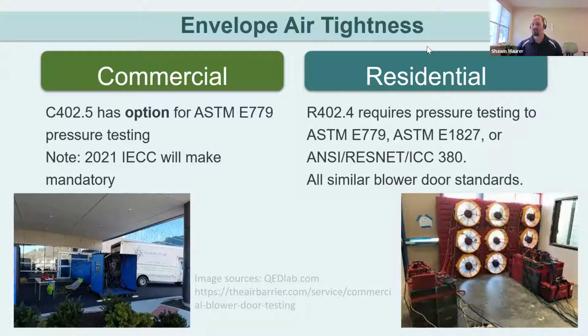Shown on screen here, you can have multiple fans linked up in the building, and you get the airflow going through all those fans to figure out the total leakage. You may do this total leakage testing for smaller commercial buildings. When you get into larger commercial buildings, you can do sampling.